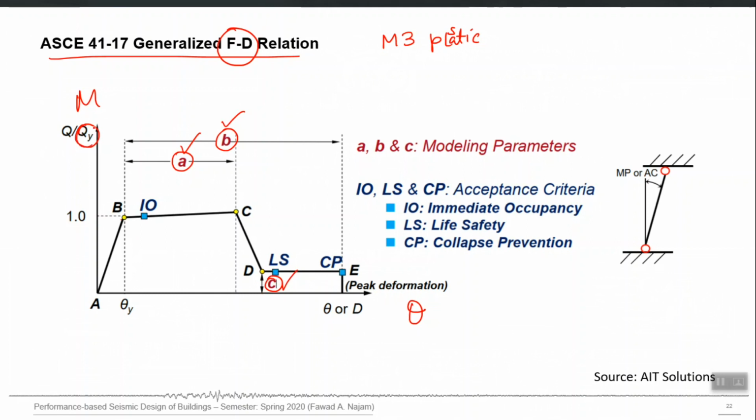Obviously, this My, which is required to construct the y axis of this curve, is a function of the amount of steel of your beam, a function of the dimensions of your beam, and Fc prime, Fy, clear cover, everything.